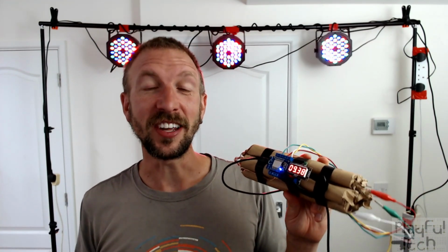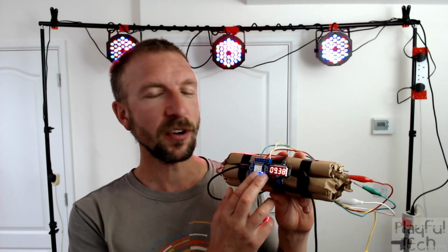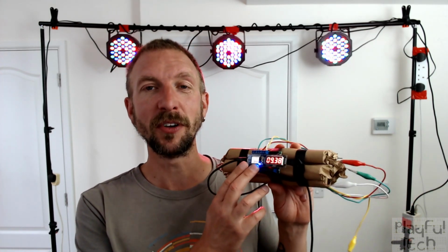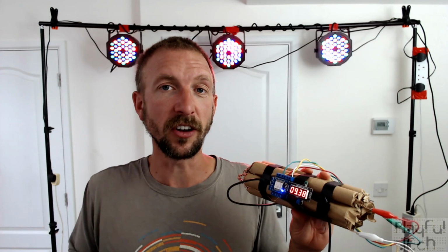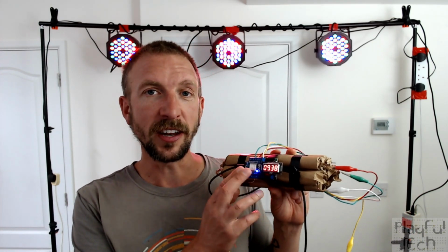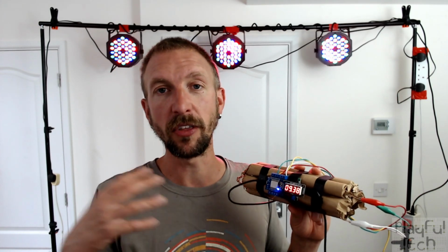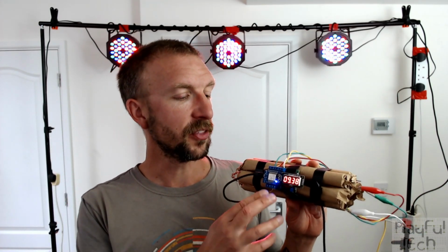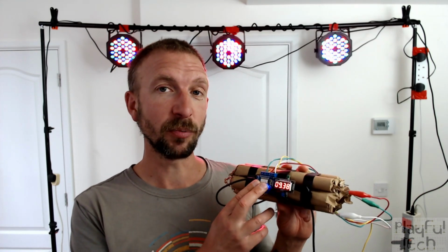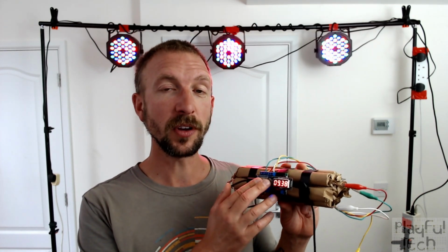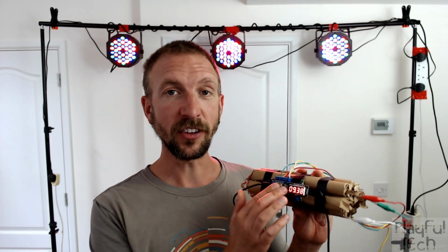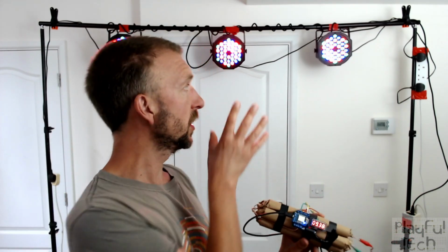Okay, so now I've shown you it in action, let me talk through some of the components in a little bit more detail. The processor I'm using in this case is a Wemos D1 Mini. This is similar to an Arduino if you're familiar with the Arduino range of boards, except it uses an ESP8266 chip rather than one of the Atmel chips. The main advantage, and the reason why I'm using it in this project, is that it has Wi-Fi built into it, and it is via that Wi-Fi connection that I'm sending MQTT messages to a Node-RED server, and that's what's controlling the light and the sound effects.